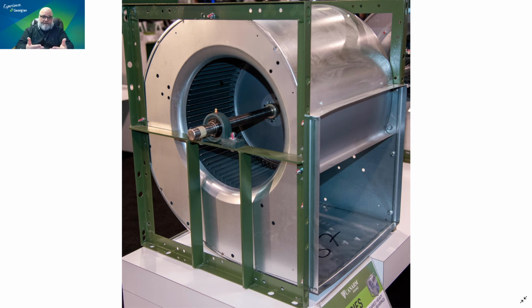If you open, for example, the door to the compartment of the blower in a furnace, you're allowing more air to go into the blower, and that forward curved wheel is just going to scoop more air and it will overload.